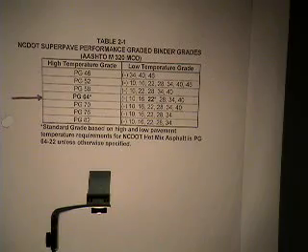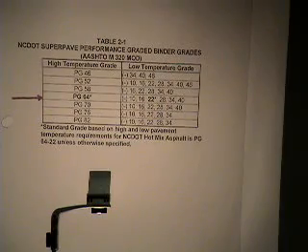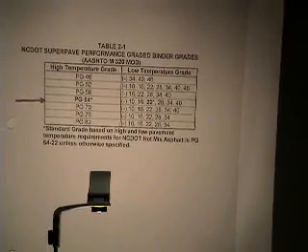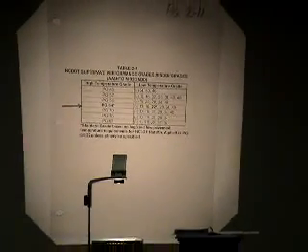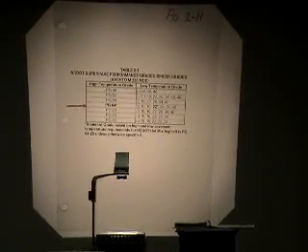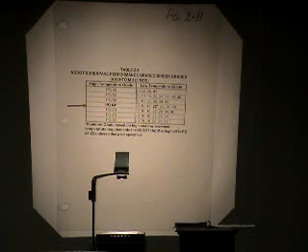Based off of certain environmental conditions, traffic loading, and things like that, we may have to step up to a PG 70-22. And then as we get into heavier or a lot more truck traffic, that's what it's based off, is truck traffic, we may go up to a 76-22. I'm not aware of using any 82 as of right now.